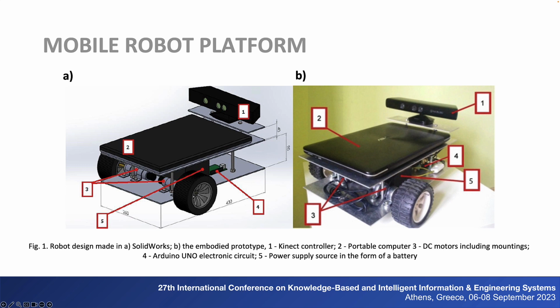The distance measuring device is the most important component of the mapping robot. It is with its help that the robot can detect obstacles and remember their position. There are several devices available to detect an object and determine the distance at which it is located. The Kinect device, for example, uses depth sensors to create a depth map of the image. The infrared emitter on the left-hand side of the device sends out a light pattern, invisible to the human eye, composed of multiple points. This pattern is then captured by the CMOS sensor. Then, the microprocessor embedded in the controller analyzes the offset of the received pattern relative to the emitted pattern. This technique is called the structured light technique.